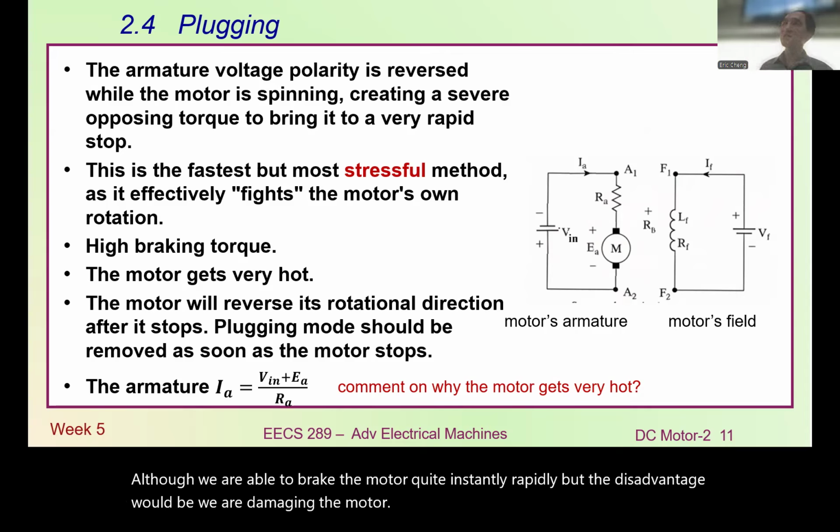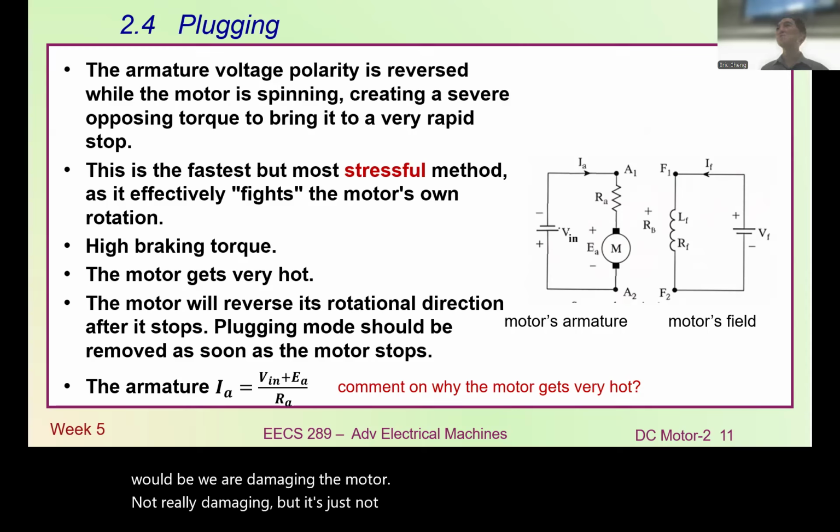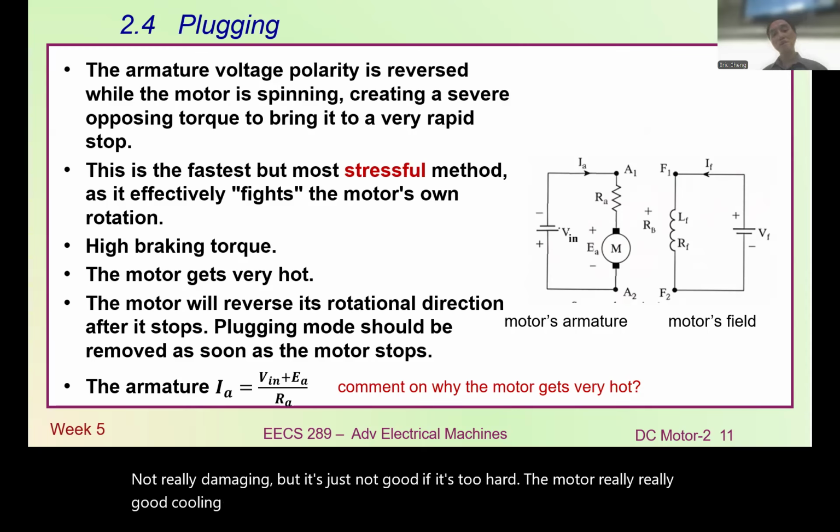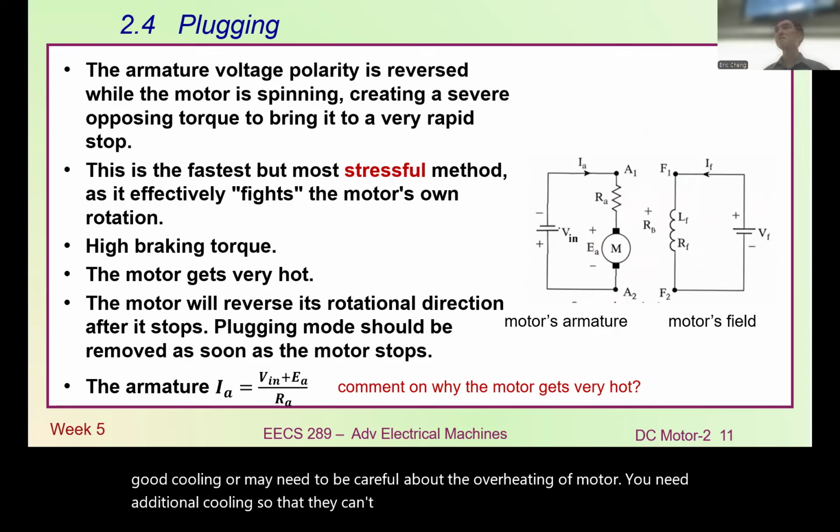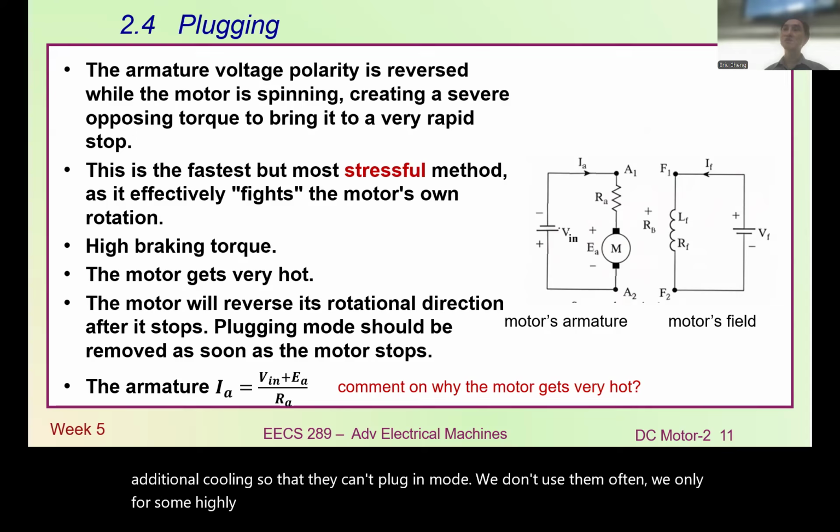Not really damaging, but it's just not good. If it's too hot, the motor will need really good cooling, or we may need to be careful about overheating of the motor. You need additional cooling. So this kind of plugging mode, we don't use often. We only use it for highly emergency cases. The motor drive has that capability, in case of any sudden braking.